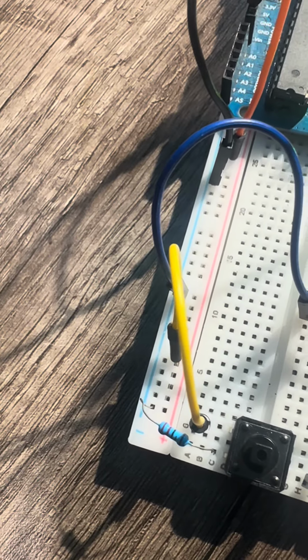This here on the upper side on the left goes into the 5-volt pin, and then here, very important, this one goes into a digital pin. I put it in digital pin 7. For the LED, I put it in digital pin 8, and I grounded it. Remember, 220 ohm resistor. So now this one is a toggle button.